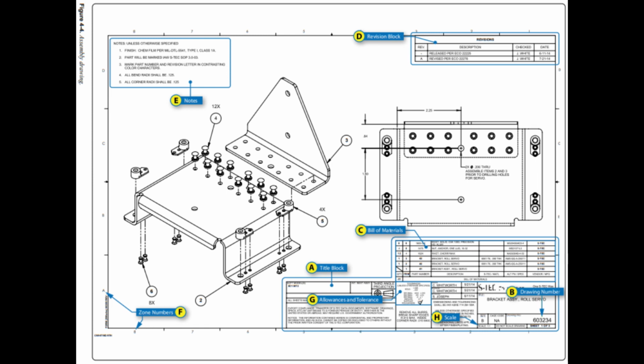Other drawing data. Revision block. Revisions to a drawing are necessitated by changes in dimensions, design, or materials. The changes are usually listed in ruled columns either adjacent to the title block or at one corner of the drawing. All changes to approved drawings must be carefully noted on all existing prints of the drawing. When drawings contain such corrections, attention is directed to the changes by lettering or numbering them and listing those changes against the symbol in a revision block.